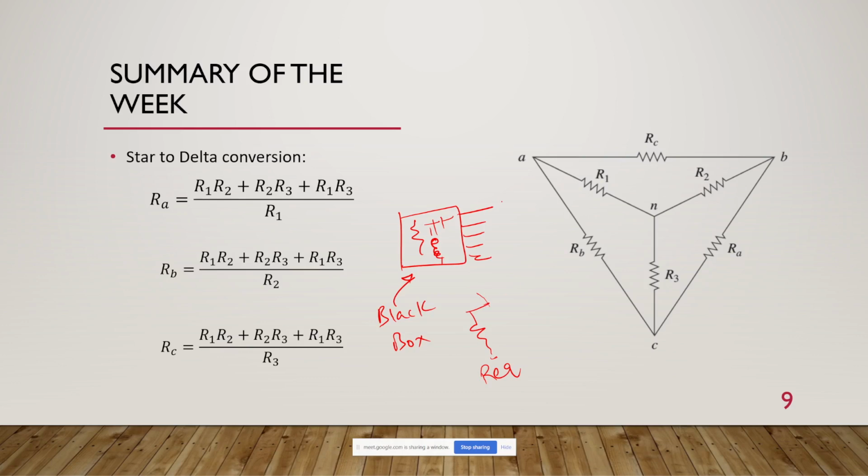if you are connecting some voltage here, is everyone with me? What is meant by finding an equivalent is that you connect a voltage at each and every terminal, and you measure the current. Suppose this is I1, this is I2, this is I3. You connect a voltage source at each terminal and measure the current. Now, if you replace it with some equivalent, then that same relationship should hold here also.